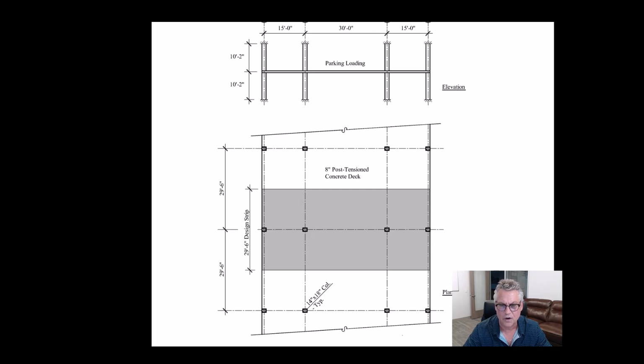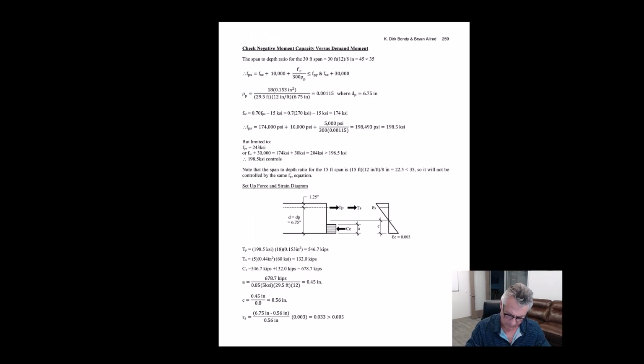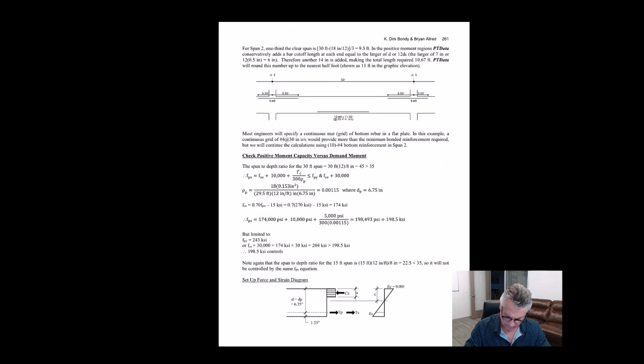So I know I've made that sound confusing. Remember, we're checking punching shear. We're doing a shear analysis. We're going to get to that shear by looking at the unbalanced moment that we have. So those moments are going to include the secondary moments. So effectively, you're including secondary effects in a punching shear stress check. I hope that's okay with you. I'm going to show you why.